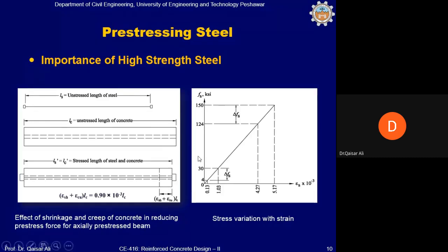Okay, now first of all, let's say the steel bar is in a stretched position, and we pour concrete. When concrete attains its full strength, then the steel rod is released from both sides. Then the steel rod, through the bond between steel and concrete, will tend to push concrete, because the steel rod is in stretched position, and it will tend to regain its original length.